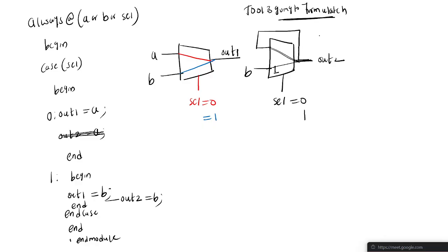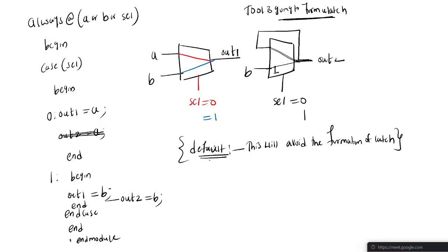Okay, so in order to avoid this, we are using the default statement in the case statement. Why are you using the default statement? This will avoid the formation of latch. In order to avoid the formation of latch, we need to use the default statement in the case statement.